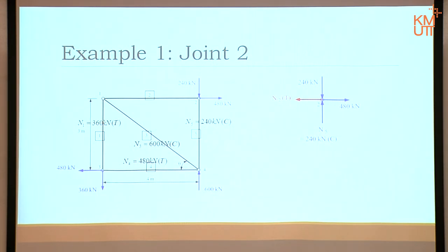If you run the joint method properly, you tend to have three equations left. Okay? One here. At the moment, we have one equation here and two here that we haven't used yet. Okay? That is usually what we use for the check. So the first equation is to find N2 first, and then we start checking. This is the first equation, sigma Fy 0. If it's 0, then it's okay. If it's not 0, it is not okay. No guessing, please, no guessing. Calculate it, because this is for check.